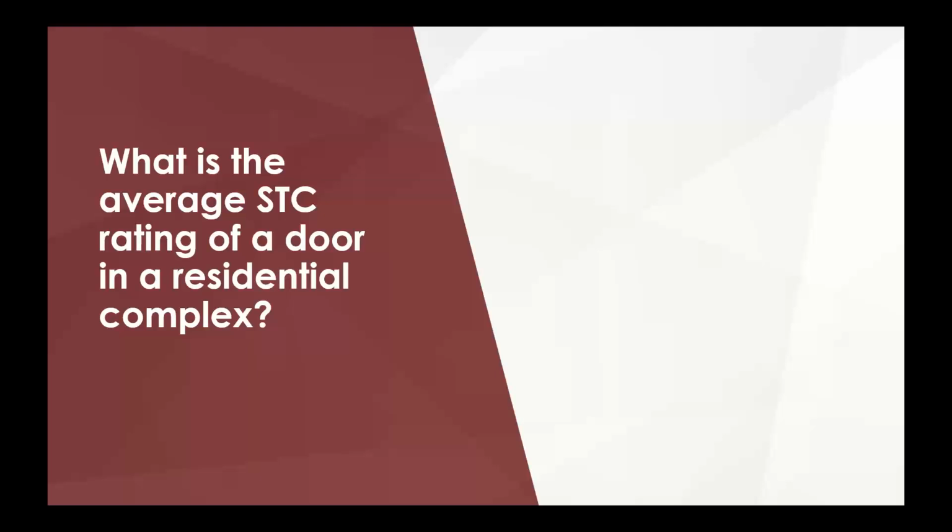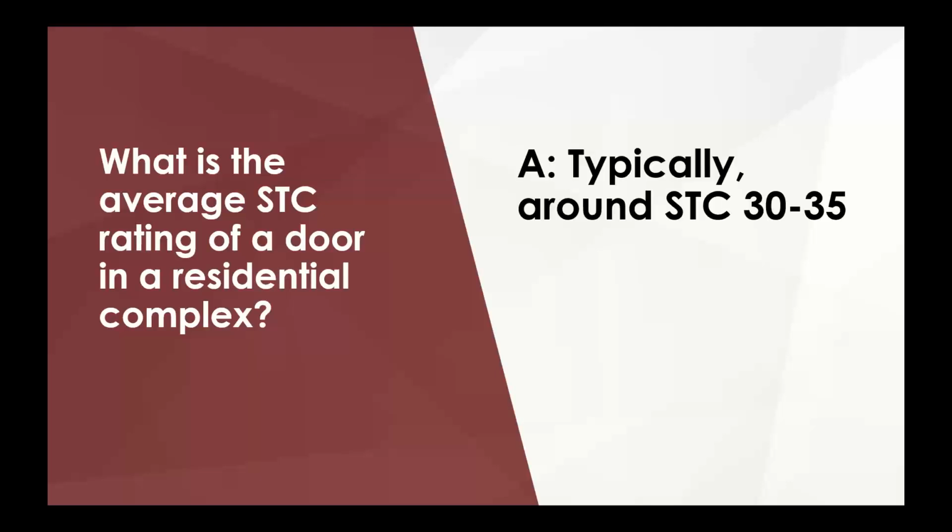And I listened to the third-party consultant say, no, you can't do that unless you could provide me with a sound report that you could get the same STC ratings with 20 gauge studs, which obviously I just showed on the slide before. You can't. So I thought that was really strange because the average STC rating for a residential door is around 30 to 35. So it makes zero difference that you're using a 20 gauge stud because it's not going to change anything, because the door's already reduced it.